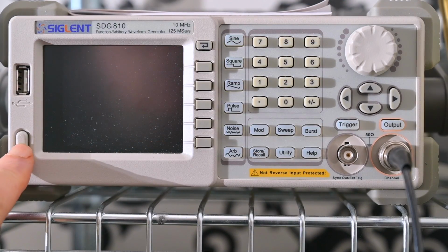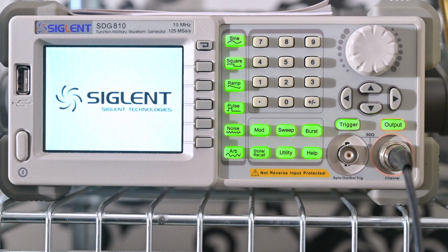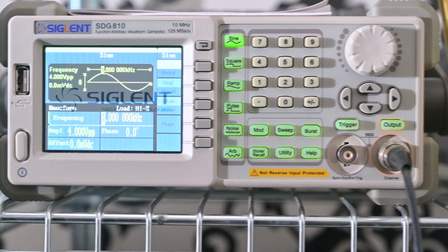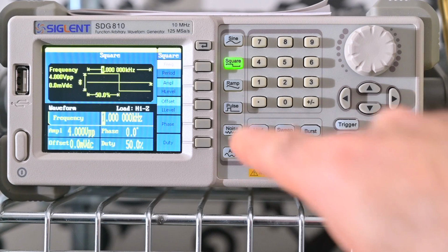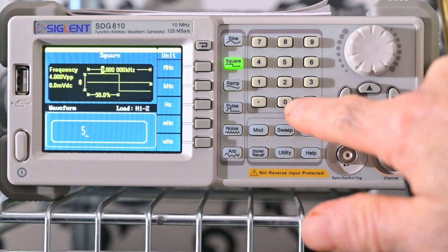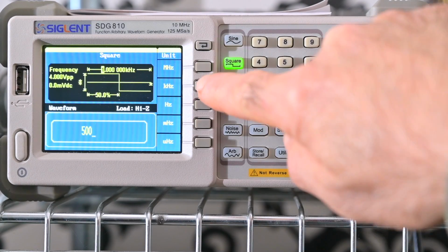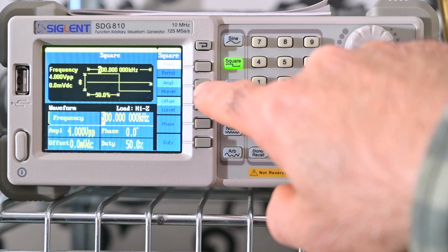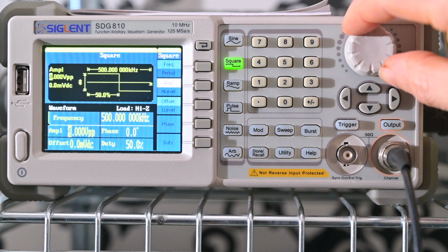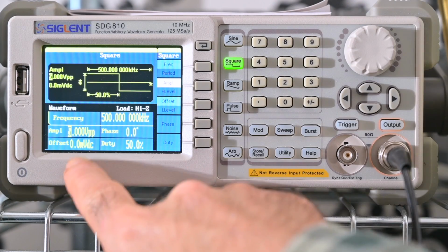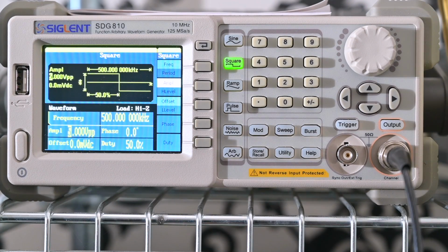And I'll use a signal generator to set up some of the signaling, pretending it's a controller, and we will be using a square wave for that purpose. We'll select the square wave, and we will work at 500 kilohertz. The amplitude that we're going to use is about 5 volts. Look over here, we have 0 volts offset, and our duty cycle is 50%.